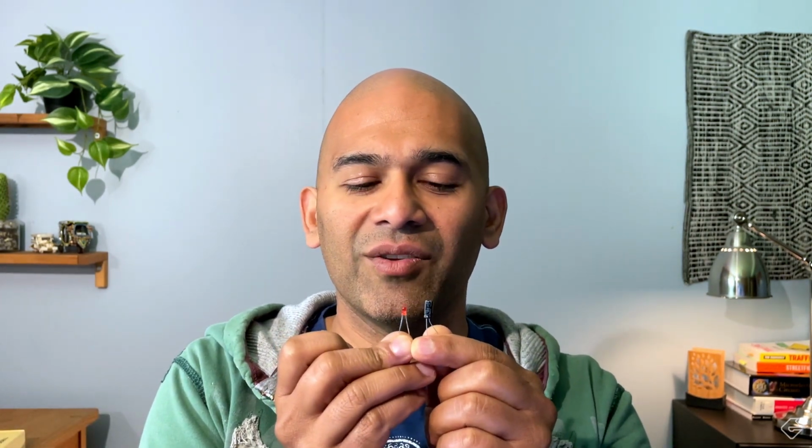And the LEDs kind of fit very close. They sit quite close to the board. And if I build everything on the same side of the board, because we're using through-hole components, these through-hole components are quite fat. They're thick. And so they're going to take up a lot of space on the board, not just these, but think about capacitors like these. They're quite tall. In fact, they're taller than the LEDs. So I will not be able to get the LEDs to show out of whatever packaging or compartment or container we use because the rest of the components are going to be too tall.